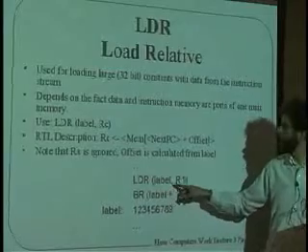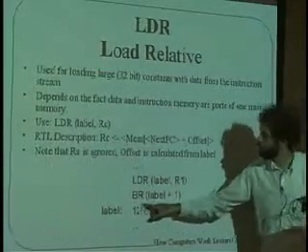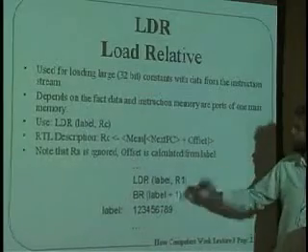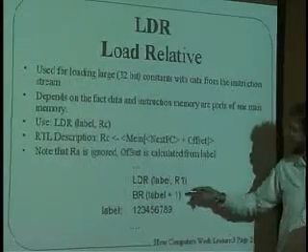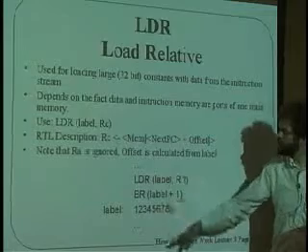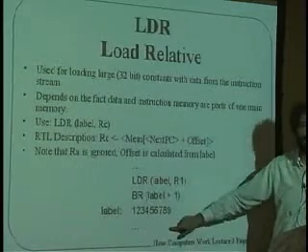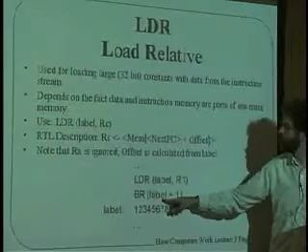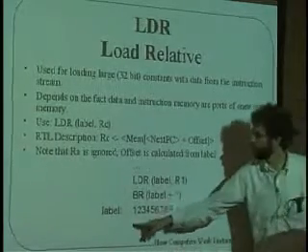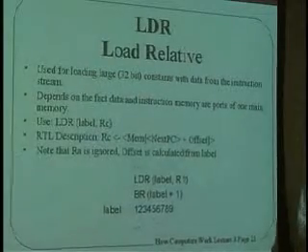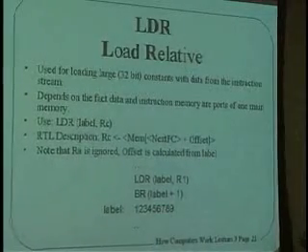What we want it to do is take this number, pluck it out of the instruction stream, and put that number into R1. Then, since the number is kind of in the way of the code here, right after we do this, we branch to this place +1, and that'll take us down here. So it's a very handy way of bringing big constants into our system.